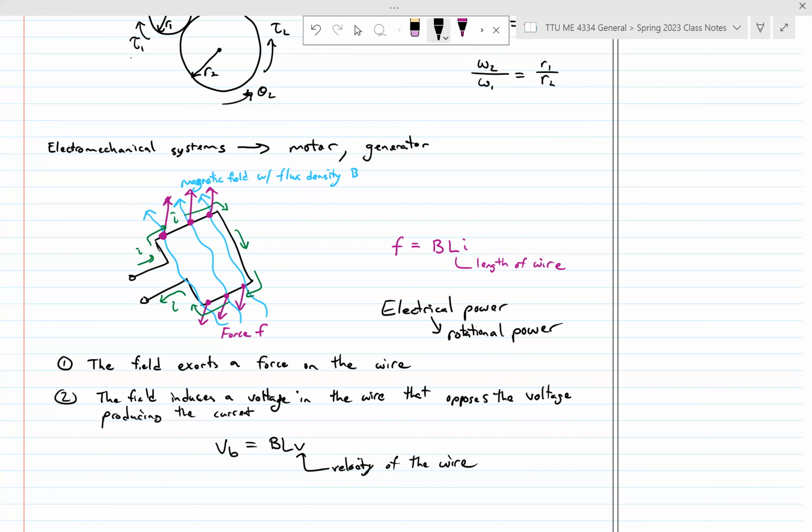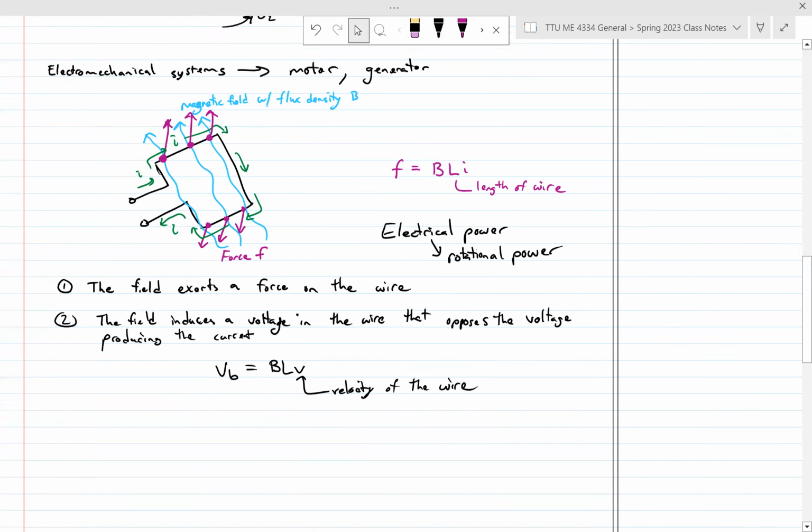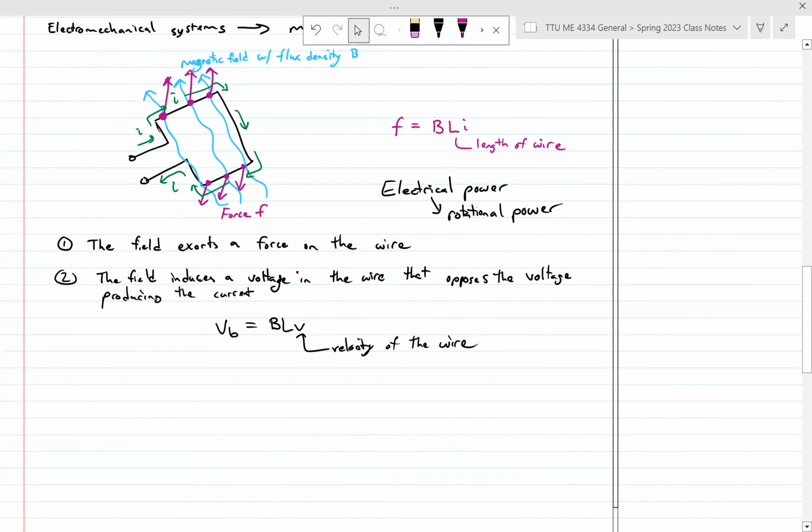And we can actually see from this relationship, if I were to take that system and start to spin it myself physically, that back EMF would generate a voltage, generate that current that's going to go back and turn mechanical power into electrical power. That's our generator mode. These are the two primary principles for how motors work, in a very simplified manner. You guys should be relatively familiar with this. So let's just push on ahead to modeling a DC motor.